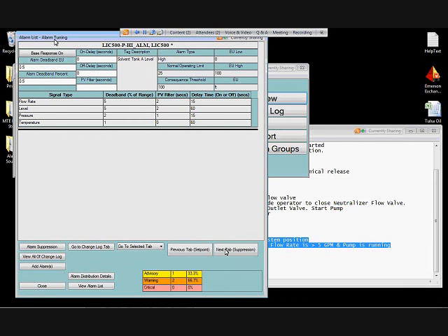Now let's look at the deadband and alarm on-off delays. And Kim had mentioned that this was a chattering alarm. And I can see that it is a level, and the deadband is set to 0.5, which I know is the default, but that's a little low for level devices. So our alarm philosophy says that we can make the deadband up to 5%.